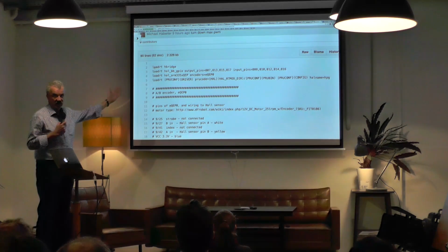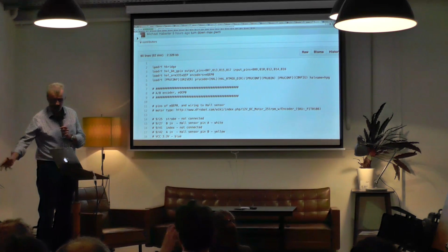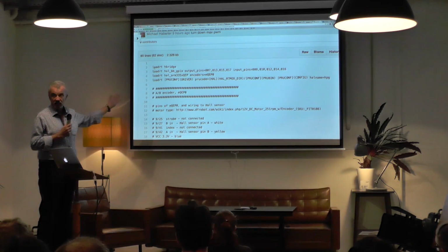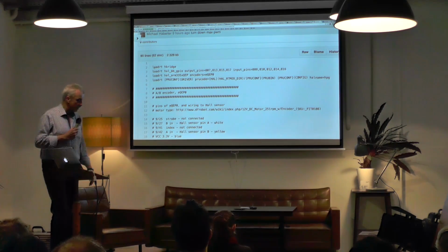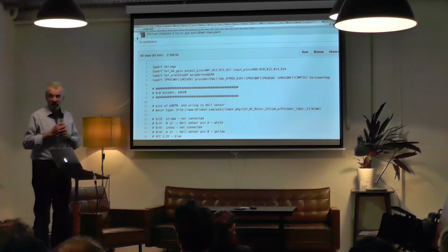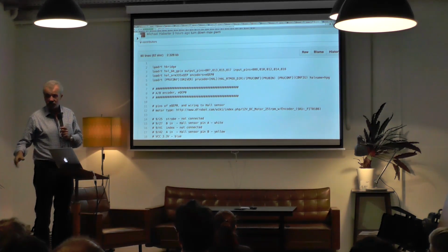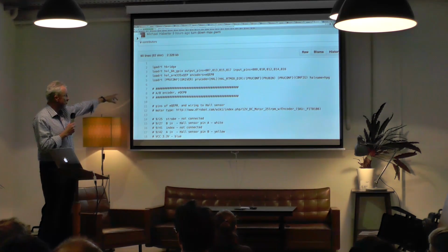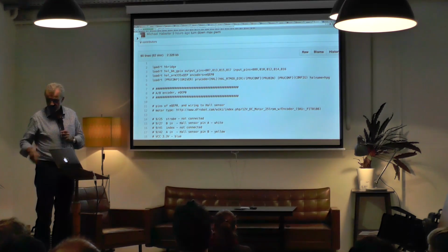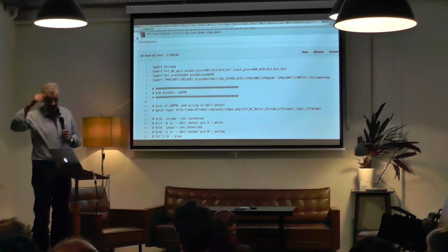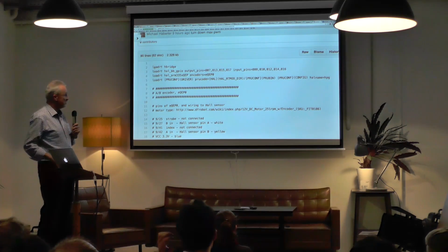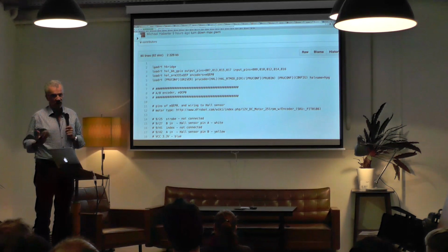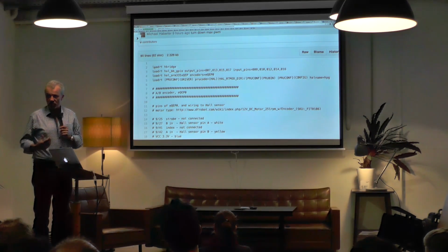The one is a signal generator for H-bridge, which drives the motor. Then there's a support for the GPIO pins on the BeagleBone. There's a hardware AB encoder in the BeagleBone chip, which is supported by the third component, and the BeagleBone CPUs, the ARM Texas Instruments Sitara, actually have two, if you will, Arduinos on steroids on board.